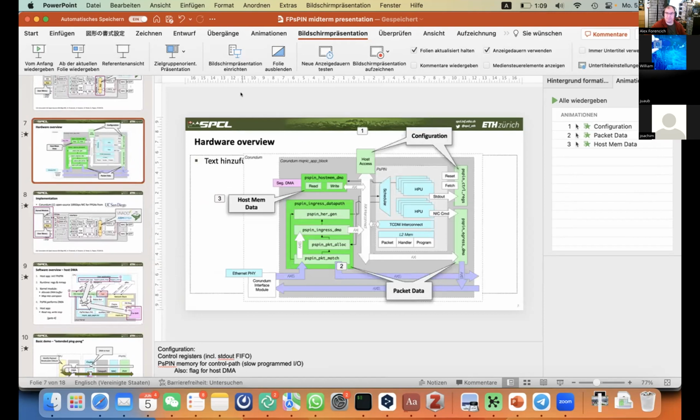I just basically reused the AXI Stream DMA in the module, but there's absolutely no concurrency going on at the moment. I take a request, send out the DMA request, then pop back the response on the write response channel.